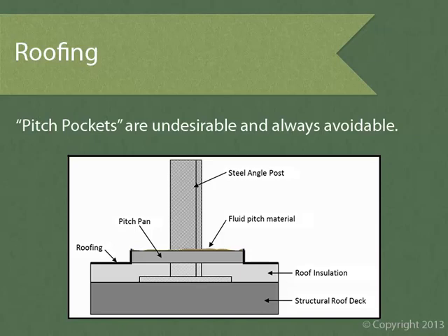A problem lies in that building maintenance workers in reality don't think about these little roof penetrations during the normal course of their duties, and the result is that pitch pockets often go unmaintained for years until they crack to a point that leaks are occurring. The use of pitch pockets is declining rapidly in popularity, and I recommend everyone get on that train. It's a good idea for you to avoid them whenever possible.